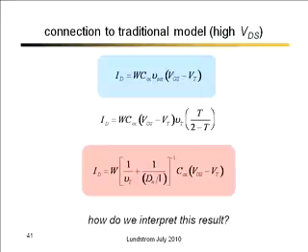That's just saying that T is lambda over lambda, not plus the channel length now, because under high bias, it's just the critical bottleneck region that's appropriate. So lambda over lambda plus script L, the length of the bottleneck. Doing some algebra, this is what we get.